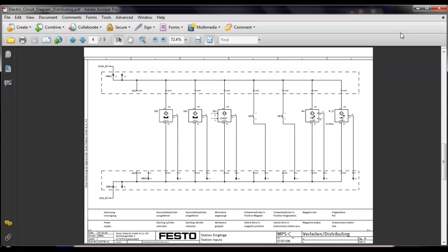So this is an electronic sensor. We have to power it up. I don't care if it's sinking or sourcing, we've got to power it up. So this is plus and minus. That powers up the sensor. This is the input. See, it's going to be black. I don't know what type it is, so what I'm going to do is look at this switch right here. It's connected to the plus, so it's going to provide plus. So these sensors have got to be sourcing, right? You understand? So this is the sourcing switch.